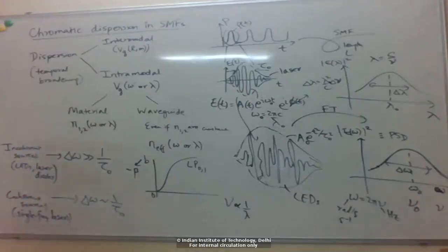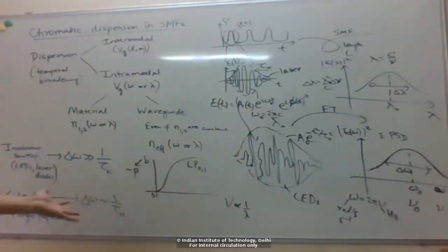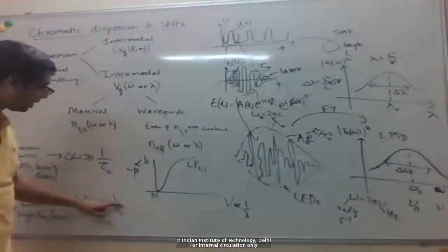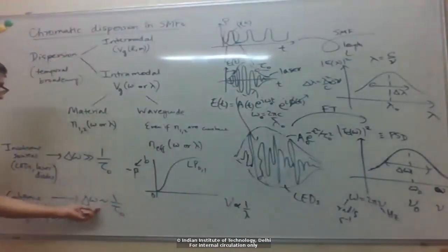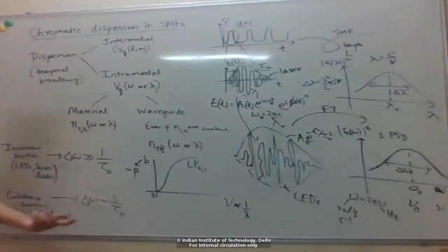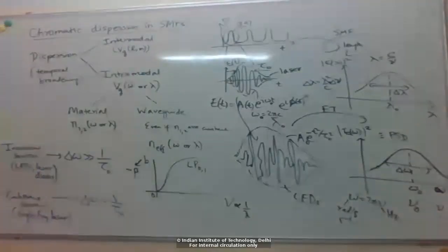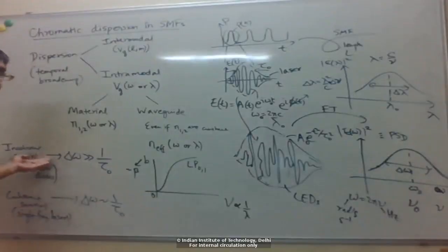Okay, so for all practical cases for the data rates we are operating at, at the frequency scale we are looking at, that's basically 0. Okay. And so again the pulse widths that we are using are typically, let's say, tens of picoseconds. So then the spectral width here you can see would be tens of gigahertz. Okay. So in this case, the spectral width you get is 2-3 orders of magnitude lower than this case.